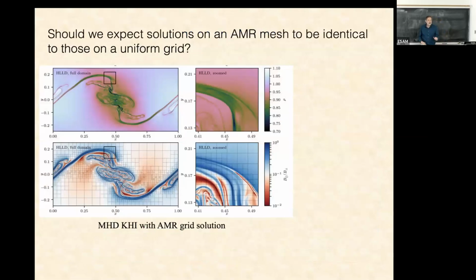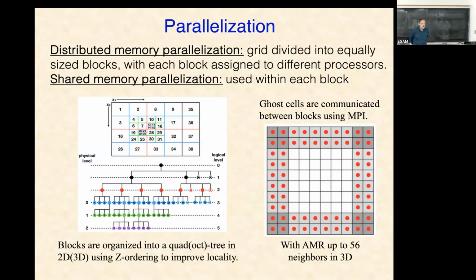So this AMR, yes. Quick question about that. Sure. What do you do when you have a fine grid next to a coarse mesh as far as sharing boundary data? I'm skipping a lot, and so that's an excellent question. Whenever you have a fine mesh abutting a coarse mesh, you need to make sure that the fluxes between the two are identical so that you're maintaining conservation. And you always believe the fine solution mesh over the coarse solution mesh, being it's more accurate.